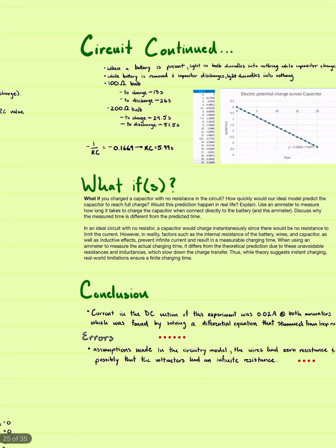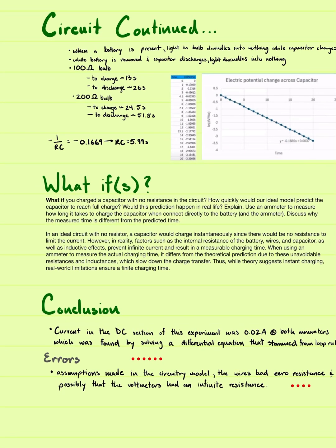In the next part, the same circuit is reconstructed such that the ammeter is parallel to the 100 ohm resistor. The resulting current is greater than the current from the original circuit because the resulting junction allows for more current to bypass the resistor, allowing the overall current to increase. In the next part, the resistance values for different components of the simple circuits were calculated using Ohm's law and compared with the experimentally determined values for resistance. The resistances of these components were calculated.